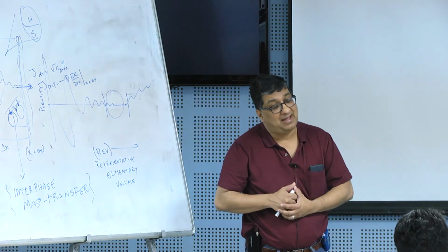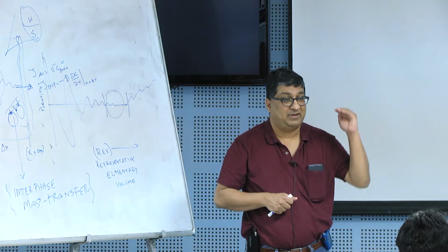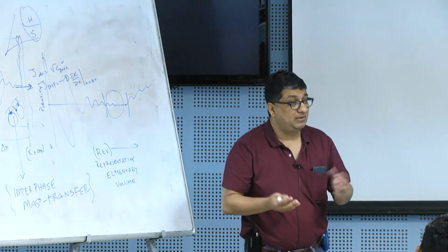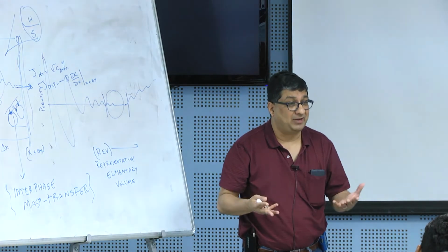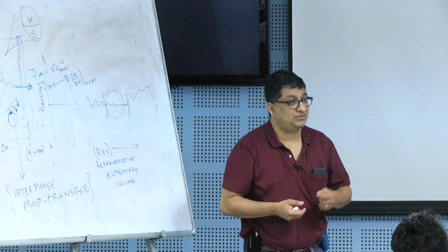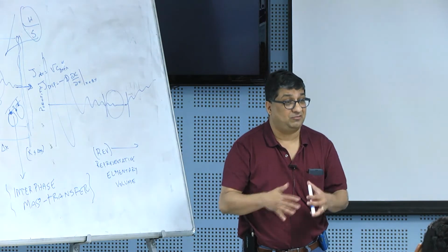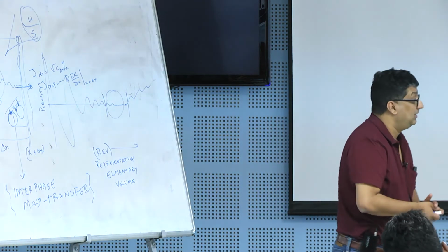Very rarely do you have a solid phase to vapor phase mass transfer, because there is usually a small coating of water on most grains, sand grains, okay, unless you have a very highly organic or hydrophobic soil like peat or histosols, which are organic soils, which you'll find near wetlands or on bogs. But generally speaking, there is a monolayer or a very thin layer of water that coats the soil, and it's extremely difficult to pull it out. Even though you evaporate it, you will still not be able to get it out, because that water is held by London van der Waals forces, which is a much stronger force at very small distances than gravity.